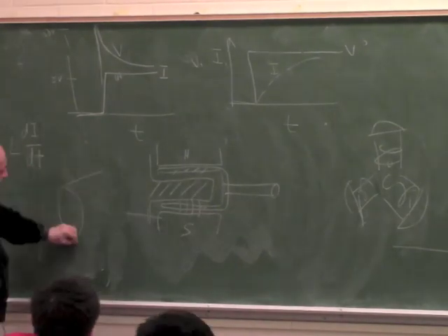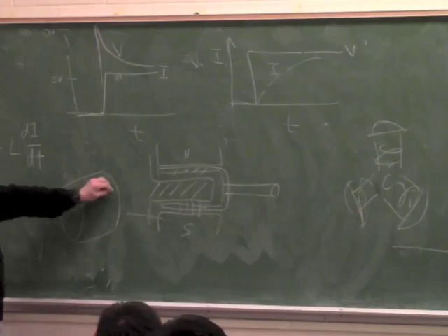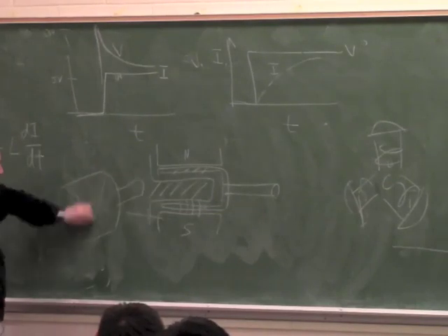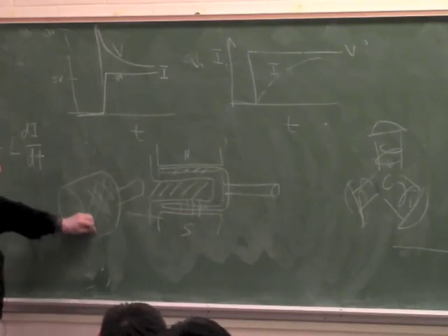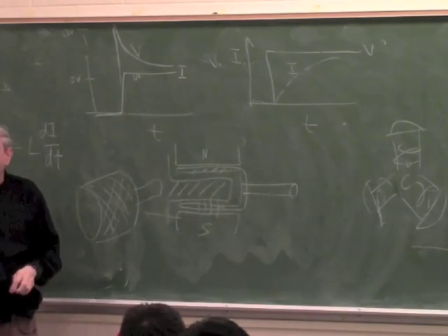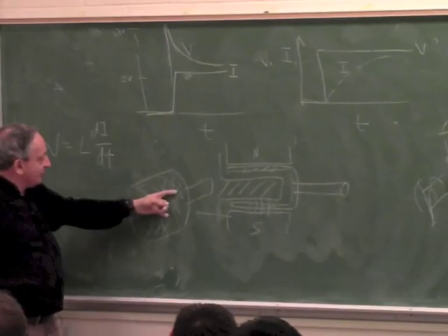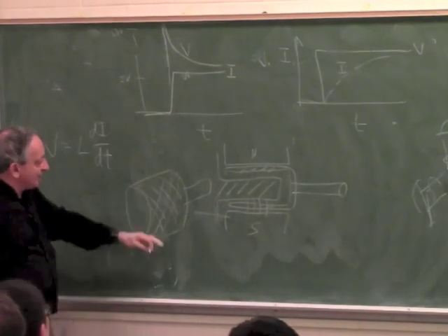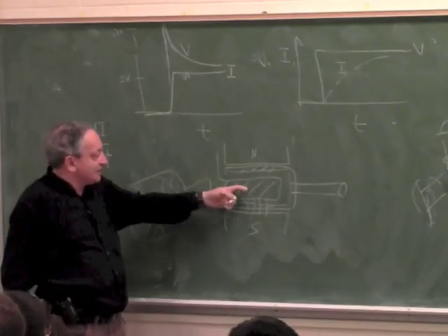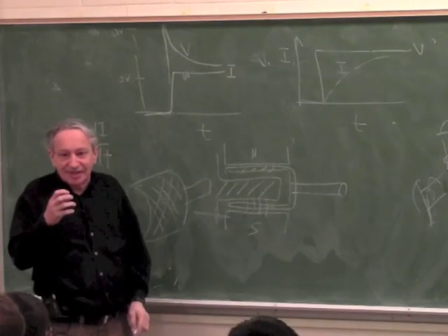So I'll draw it in 3D. The rotor looks exactly like a cup, open from this side and has a shaft. And it's wound with wire and epoxy to be self-supporting. Okay, now inside here you either put a piece of steel or a magnet, and outside you put a magnet. Most of these motors are reversed, the magnet is inside just to minimize size.